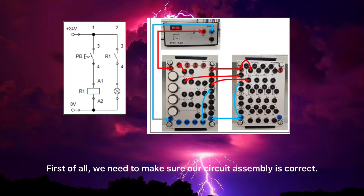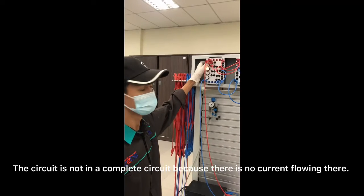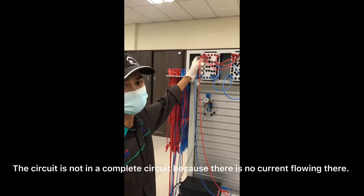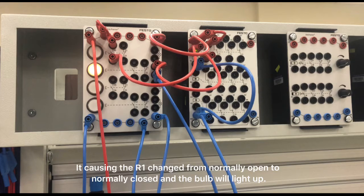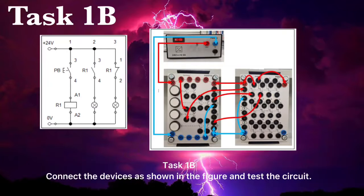First of all, we need to make sure our circuit assembly is correct. The circuit is not complete because there is no current flowing. But if you press the push button, the current will start flowing and cause the coil to energize, and it will produce a magnetic field. It causes R1 to change from normally open to normally closed, and the bulb will light up.